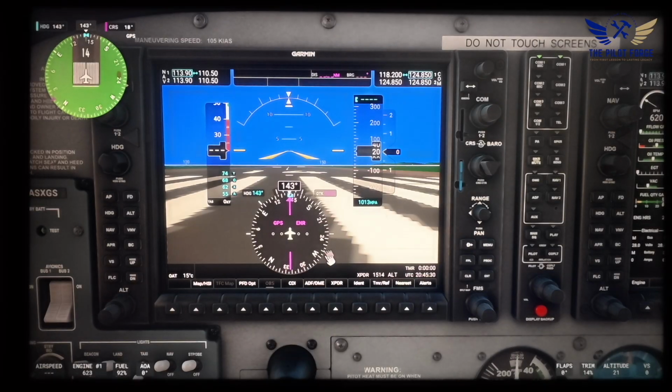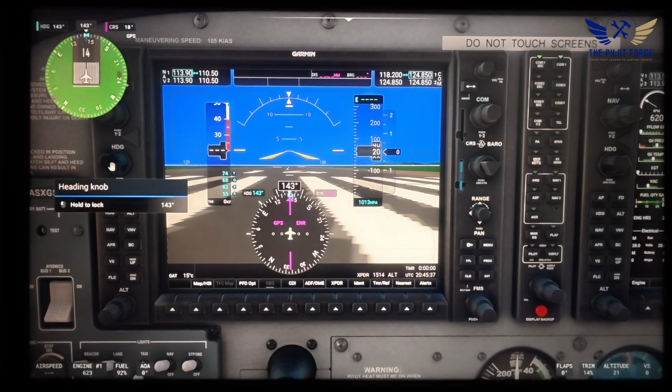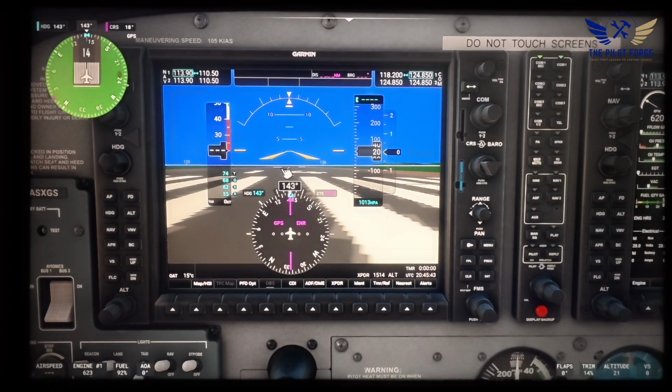See that? That is the direction indicator, or the directional gyro. See that blue bug? That's called the heading bug. That's selected by this, and when you press it, it aligns with your current heading. This heading also coincides with your runway direction, which is 14. Okay, 140, 141, 143, it's all on the aerodrome plate.